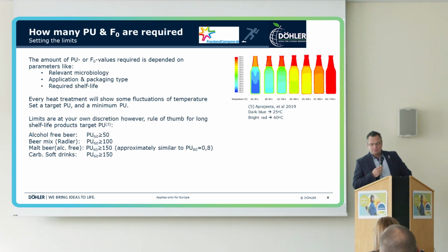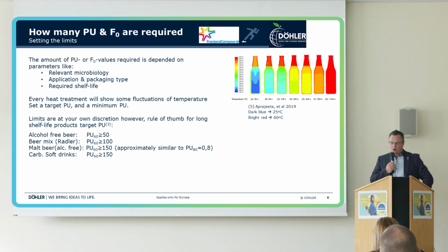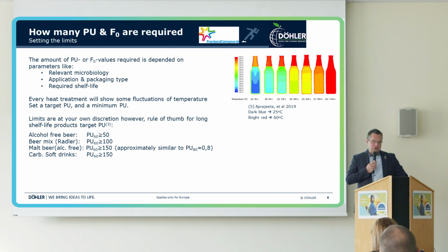And by doing that, there are two very common formulas. These formulas are described in several pieces of literature. However, not often it's understood where they come from. Well, the time is simple. Basically, the flow of your production line in cubic meters per hour, calculated to seconds, and then the volume of your holding tube. That part is easy.